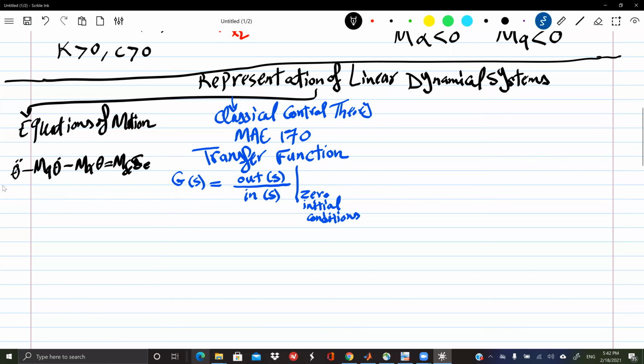Well, the Laplace transform for us here in this course is so easy. Why? Because you just replace each dot with S. And actually, the fact that we have zero initial conditions helps you in doing that. We cannot do that if we have non-zero initial conditions. So luckily we have zero initial conditions. Simply any dot you see, put S in front of it.